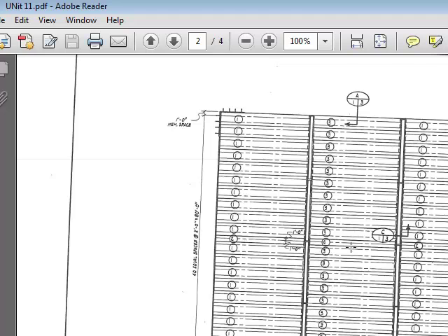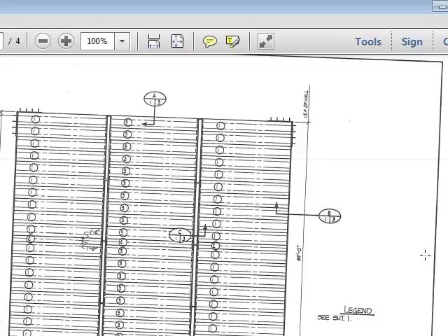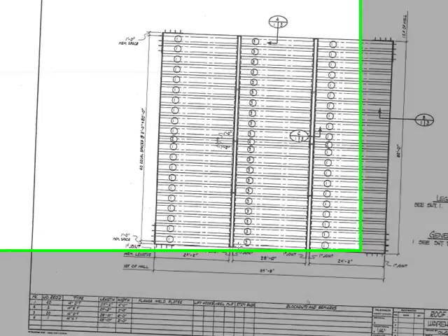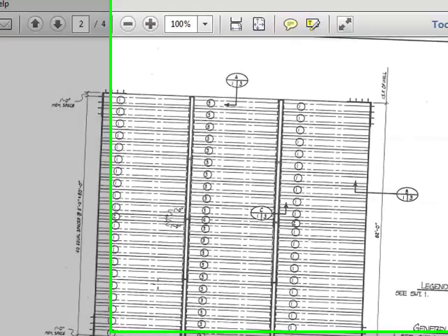Right here? Well, that's because it's like the 2, except you connect it on both ends. So that's one thing. When you make your schedule down here, you've got to study all the different scenarios. It may be the same length and everything, but there may be something slightly different. If it's slightly different, you've got to give it a different mark, because they'll need to construct it differently in the factory.